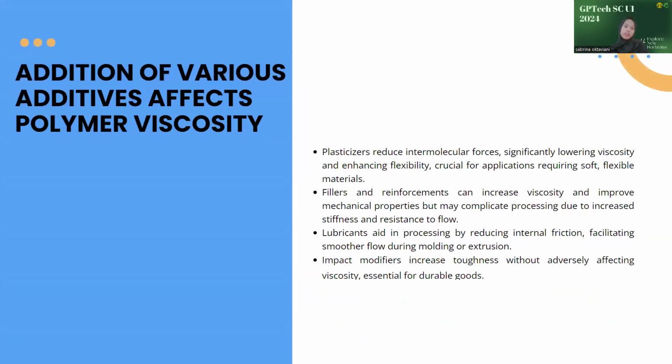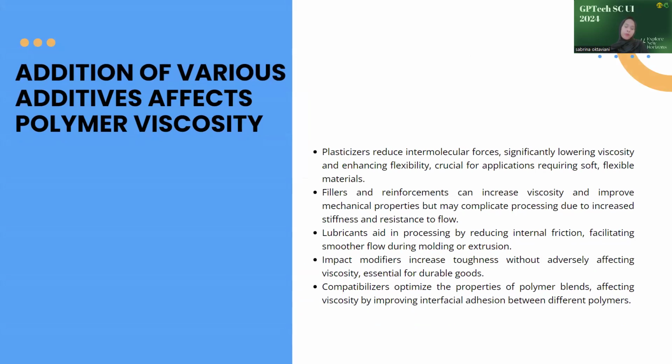Next is the effect of various additives on polymer viscosity. Plasticizers reduce intermolecular forces, significantly lowering viscosity and enhancing flexibility, and are crucial for applications requiring soft, flexible materials. Fillers and reinforcements can increase viscosity and improve mechanical properties, but might complicate processing due to the increased stiffness and resistance to flow.